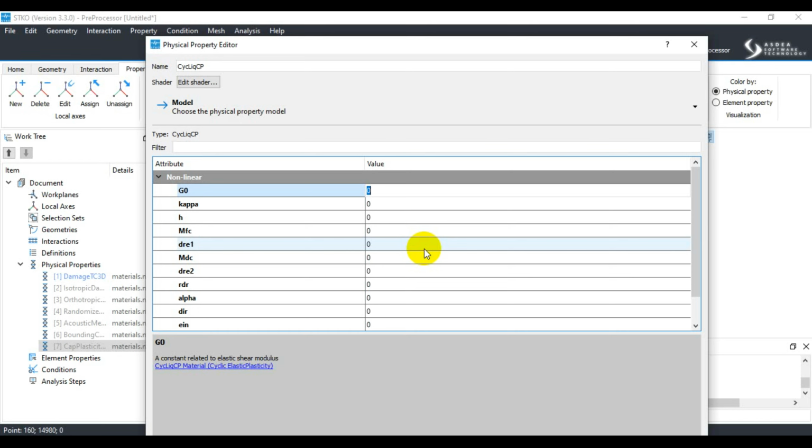Another feature of this model is bounding surface plasticity. In other words, the permanent deformation is modeled within a framework that considers limits on how much a material can deform plastically before failure. Also, this model has reversible and irreversible dilatancy. Dilatancy basically refers to the tendency of the material to expand when subjected to loading. The model accounts for both reversible, that is temporary, and irreversible, that is permanent, dilatancy effects.